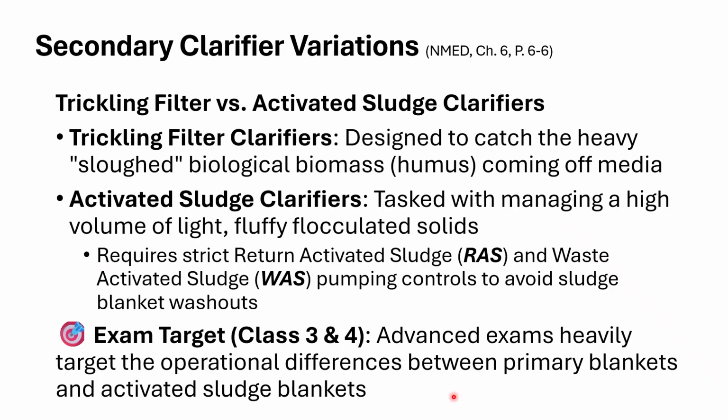Okay, so for levels 3 and 4, these exams, they're going to ask you a lot of operational difference questions between a primary blanket and an activated sludge blanket. Be prepared to know the differences as well as management techniques for both a primary clarifier sludge blanket as well as a secondary clarifier sludge blanket.